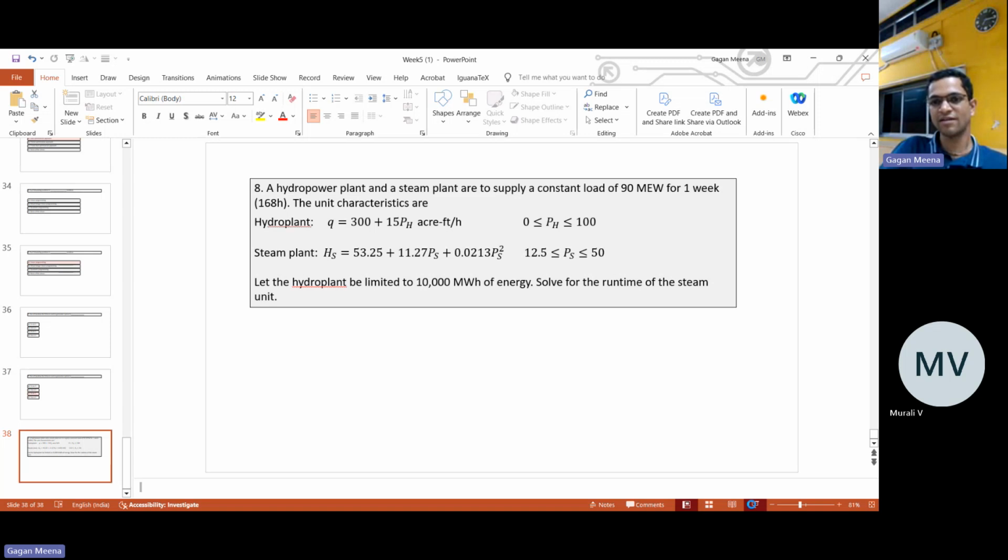Only for 5 to 6 hours, and only when there is excess renewable generation. What happens with solar, and with wind also, but mostly solar, is that when temperature is very high, the efficiency of solar is less, and when temperature is very low, irradiance itself is low, so output is low.